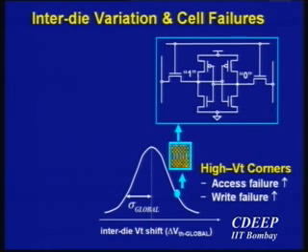Now, if you really then put in redundancy, if you do ECC and so on, by the way, remember ECC is not really for this, ECC is more for soft errors. But if you do put in all those sort of things, then you can improve it to about 70 to 75%. But it turns out it's very difficult to go to 90, 95 or more. So there is a need to look at techniques which can actually give you that improvement.